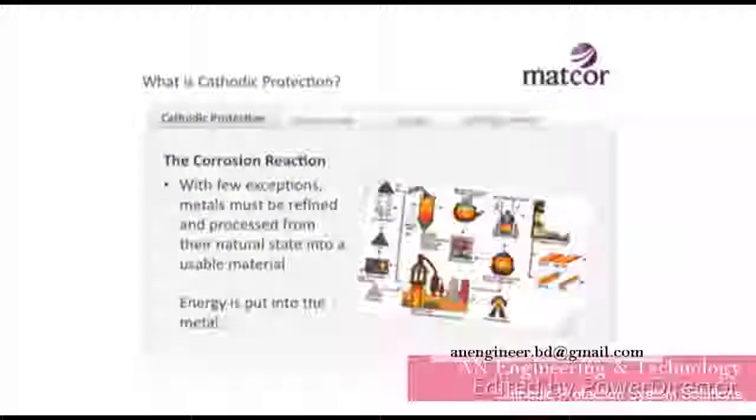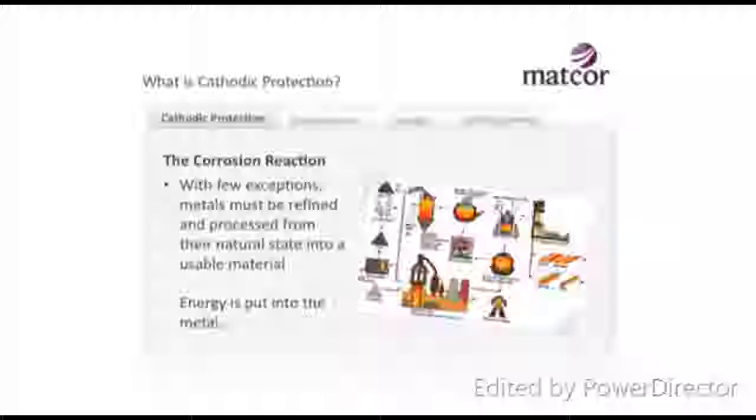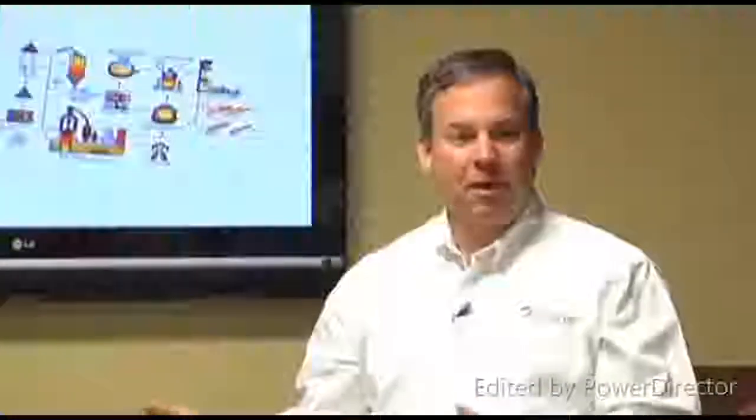So what is corrosion? And as you can see from this slide here, corrosion is a reaction. And with very few exceptions, all metals take a lot of energy to put into them to be able to use them. Okay? You don't go out and find a carbon steel piece of rebar. What you mine is iron oxide, and you have to turn that iron oxide into a metal that you can use. And that's true for basically every metal. There are a few exceptions. Gold, silver are the two notable exceptions. Gold, you actually find gold as gold. But almost every other metal in nature is found as an oxide and has to be processed. And that processing is a process of putting a lot of energy into metal.